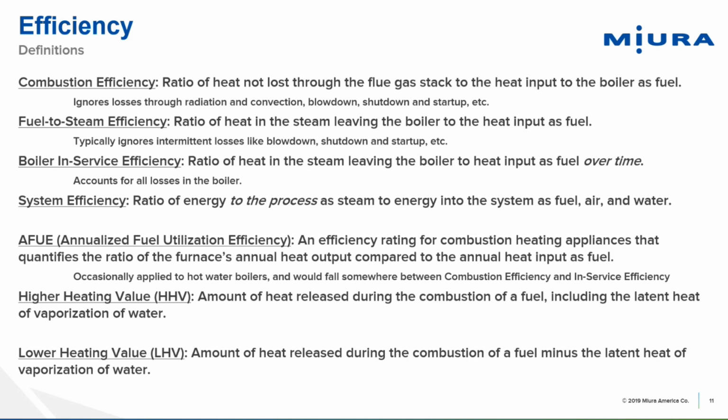Last couple, higher heating value, HHV, that one's probably a well-known term to you guys. That's the amount of heat released during the combustion of a fuel that includes the latent heat of vaporization of the water. So that's kind of the whole picture of how much heat is contained in that fuel. The lower heating value is the same, but it's ignoring the latent heat of vaporization of water. So if you put efficiencies in terms of LHV, you're going to show much higher efficiencies. I think Europe and many other parts of the world use LHV. In the US, we typically use HHV. So it's just good to be aware of what you're looking at there.